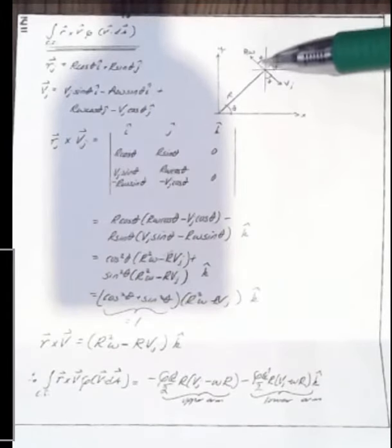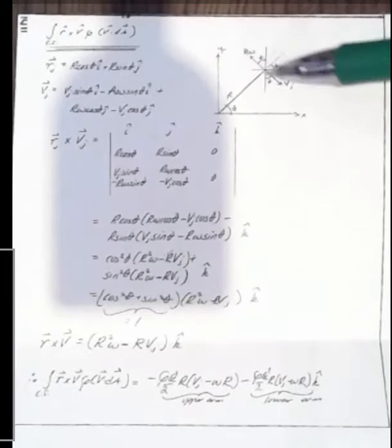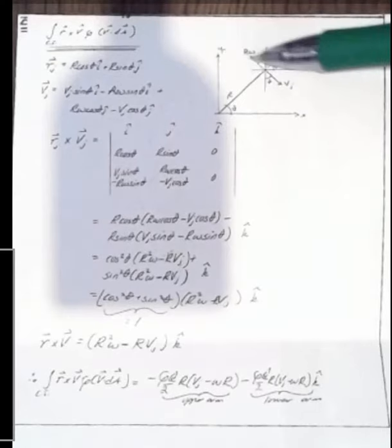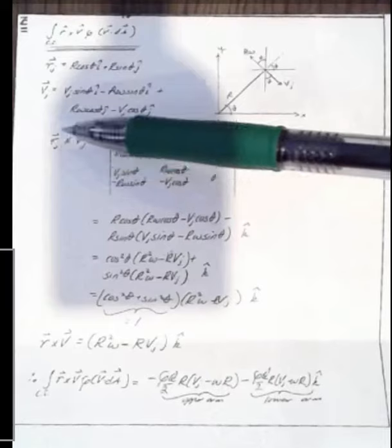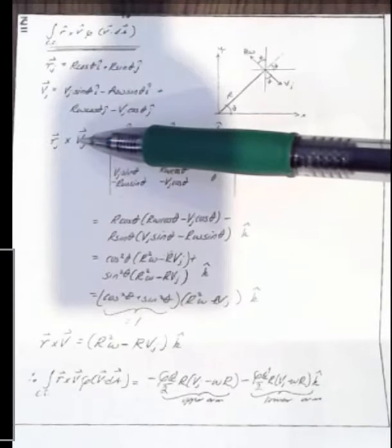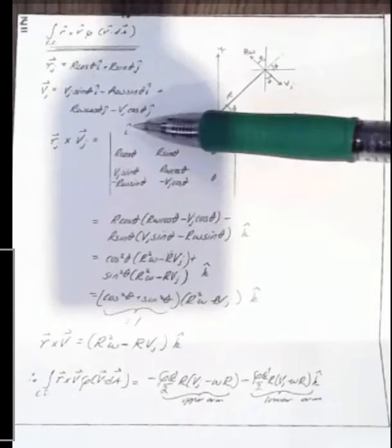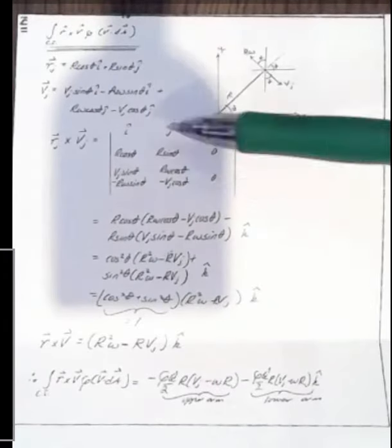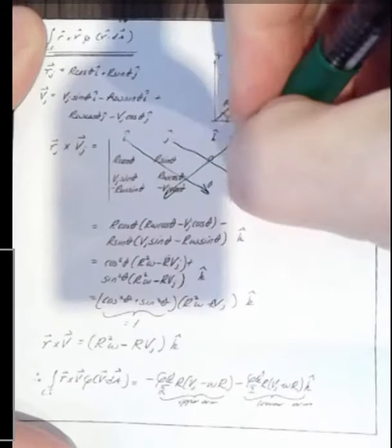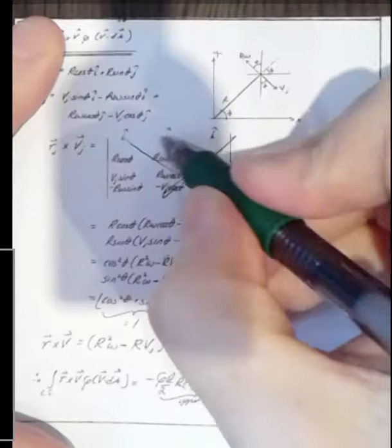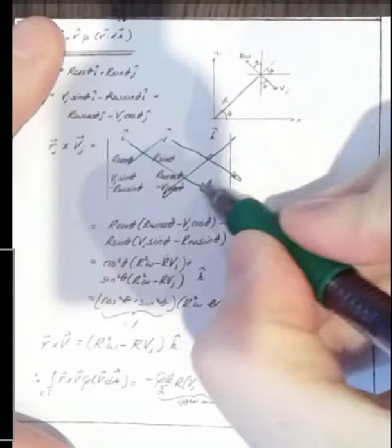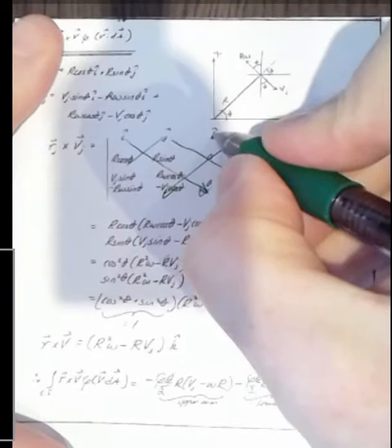And here's our drawing for the velocity of the jet and then the velocity of this point. Now we have to do r cross v. Same thing as before. The i is a 0, and going back there's a 0, so nothing in the i. j has a 0 that way, j has a 0 coming that way, nothing in the j.